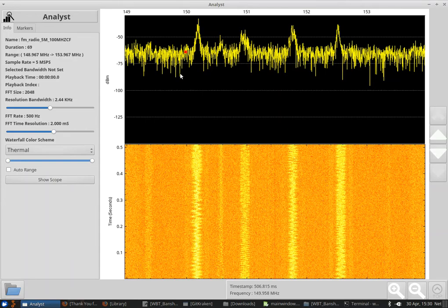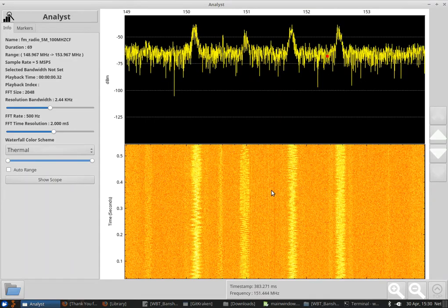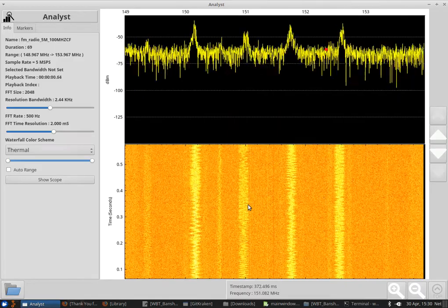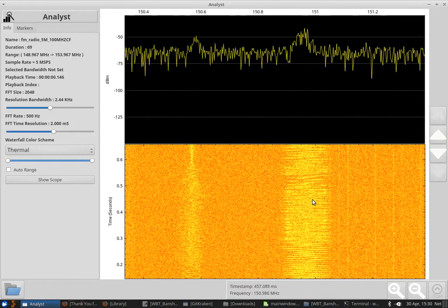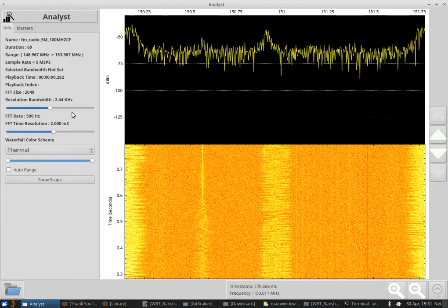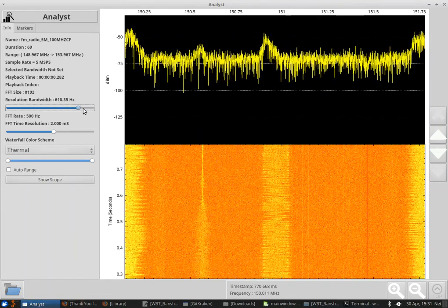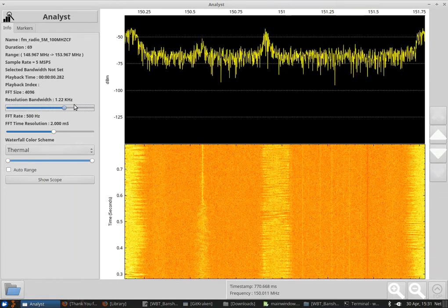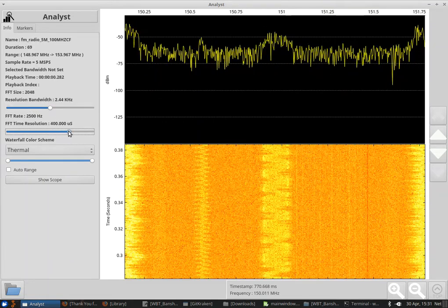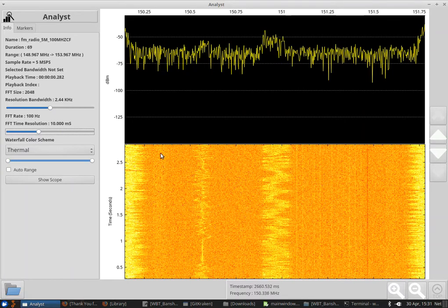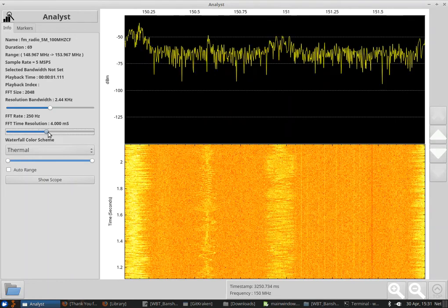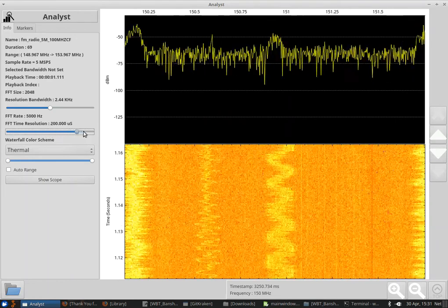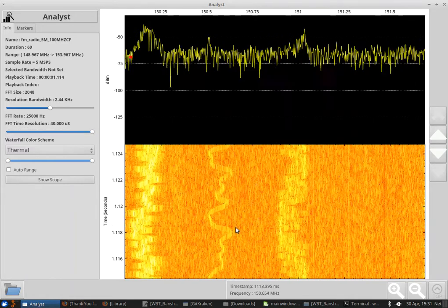As you can see, we've got the standard FFT display on top, waterfall display on bottom. What's nice is you can click and pan around, zooming in and out of the data to take a close look at some of these waveforms. We've also got a slider for the FFT resolution, so you could start increasing frequency resolution or increasing time resolution. Right now, this is showing 100 hertz per line, or we could move it up to 500, 1,000, 2,500, I think up to 25,000 hertz per line.